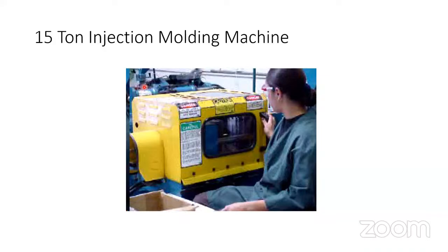Now see here, the tonnage. What type of tonnage do you want? One tonnage, two tonnage, three tonnage, as per what type of clamping force you want. Clamping force is always measured in tonnage, and we have to measure that. That's why I told you the clamping pressure should be higher than the injection pressure. What will happen?